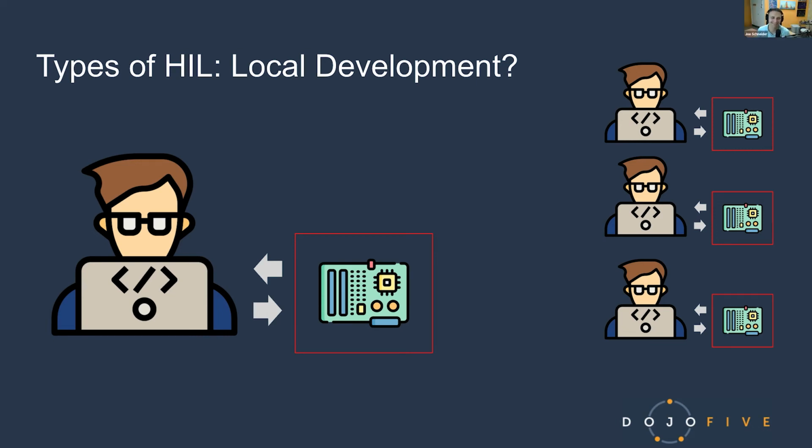It's true that it has the hardware component, but is it really in the loop? Because what I have seen some teams do is basically have two versions of your firmware. One version is the firmware that you are going to release, and another version is the firmware that you are going to use to test. And they do different things, right? Because they basically run the test. You need to make sure that running the test on hardware doesn't interfere with the correct functionality of the device.